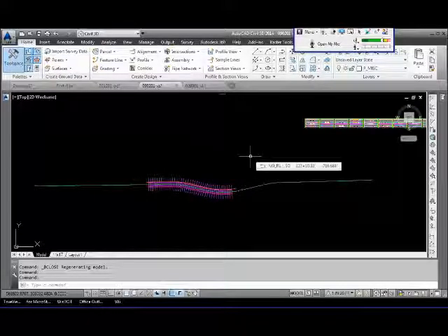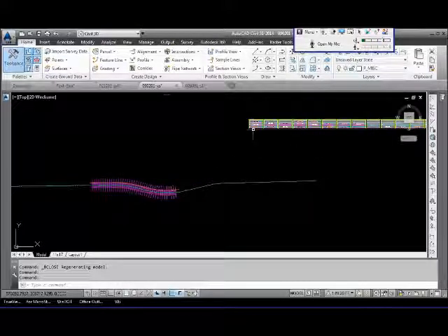The reason that I chose to make my own block is so I can easily share this to another drawing, and if I want to label that reference line in another drawing, I have that block already made. There are built-in user text options that you can use if you really just want to label one thing in that drawing. You can definitely use the user text blocks and the user text style, and you don't have to worry about creating your own blocks and whatnot from there.